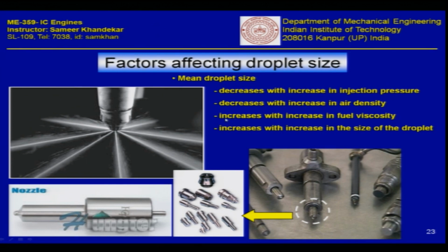Okay. Then the third point is that it increases with increasing fuel viscosity. You have to understand that if the viscosity of the fuel is not right, that means it is, let us say, highly viscous, then in spite of the fact that you are creating a pressure, this viscosity will not lead to proper spray formation. So, in all engines, the temperature of the fuel up to the inlet of the fuel nozzle has to be very precisely maintained.